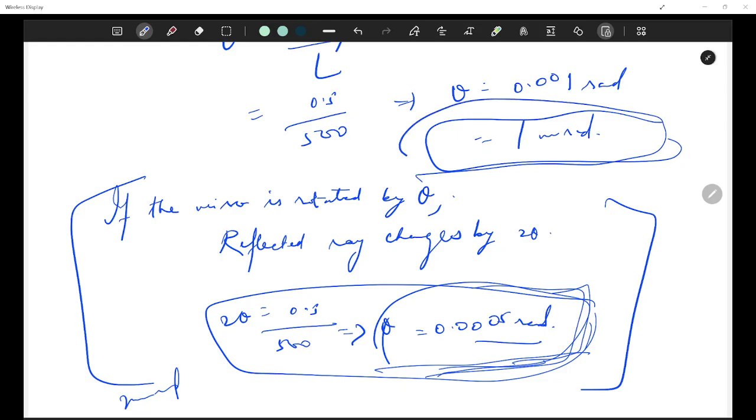So 2 milliradian is a reasonable engineering compromise, okay? And we should go by it. So the small angle relationship that we use, shift is equal to L theta, that was important. And reflection doubles angular error. Longer distance means tighter accuracy. Smaller receiver means tighter accuracy. Hence, it's 2 milliradians approximately. Okay.